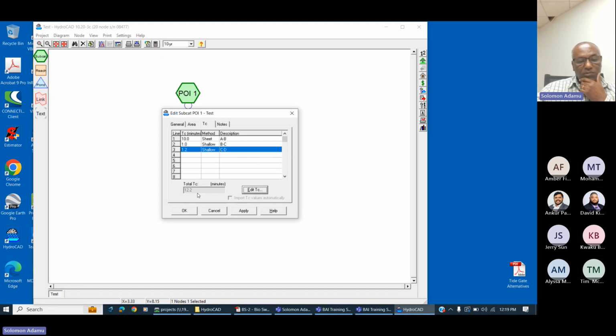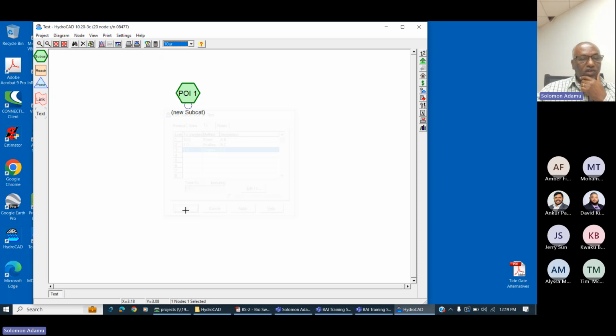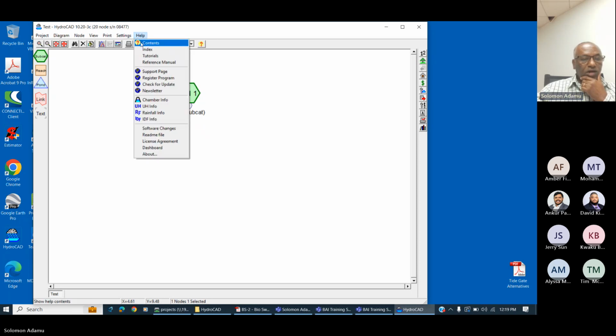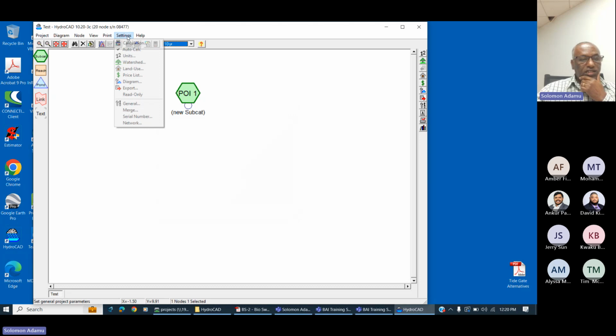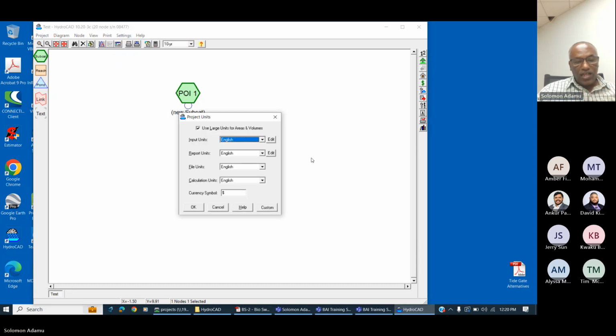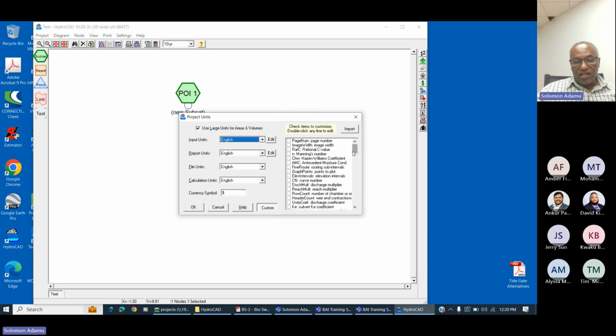By the way, we can change the time of concentration from minutes to hours. You do it here in units, and we are using the English system. For time of concentration, you look up the custom, and you'll find it somewhere under custom, time of concentration.